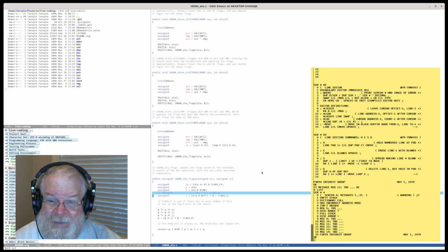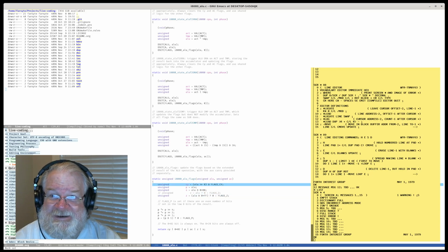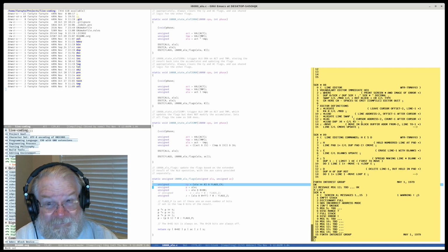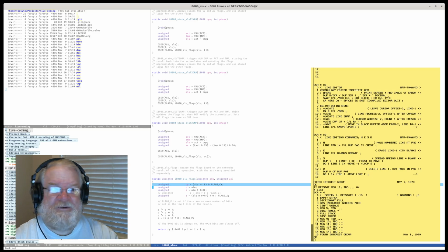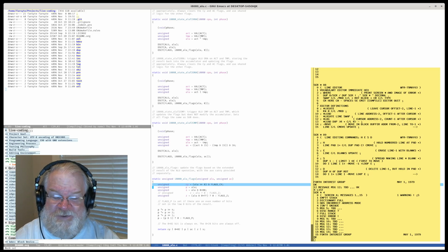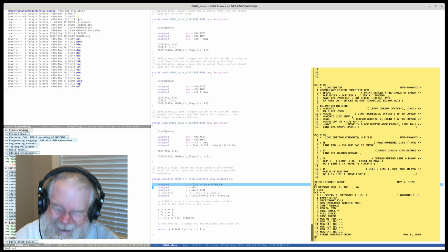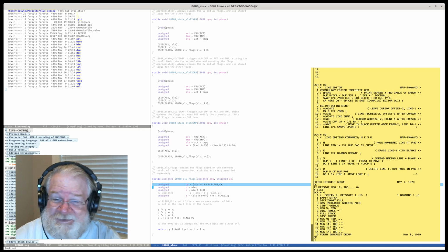What I forgot was the value coming in for the ALU also contained the carry flag. It was the extended ALU result in 9 bits, which includes the carry in bit 8. So any ALU result whose extended value was 256, I would not set the Z flag. If you are comparing 2 bytes ignoring the top bit, the easiest way to do that is to subtract them, then add A to itself, which comes up with a 0 if A had the most significant bit set and nothing else.